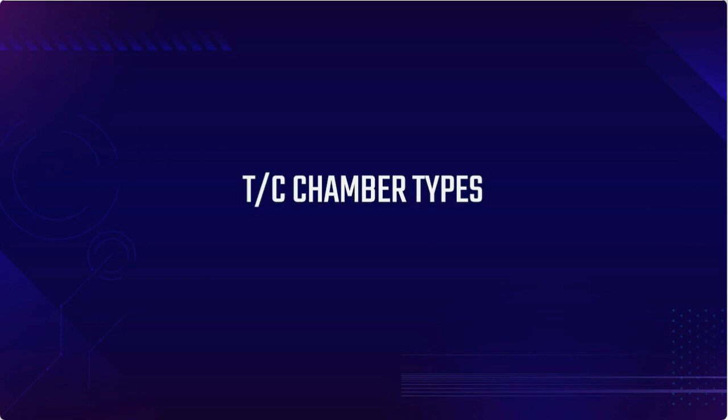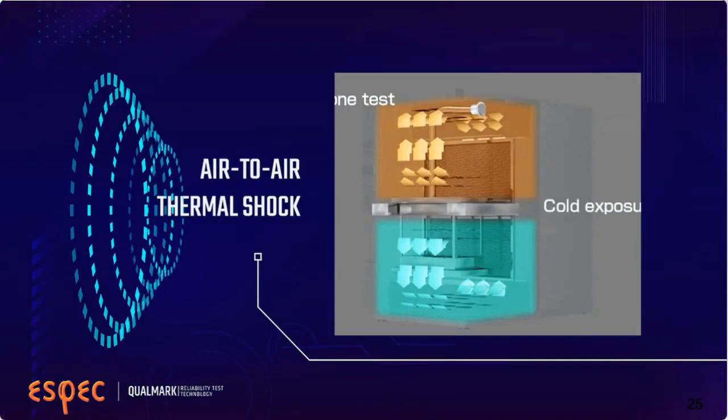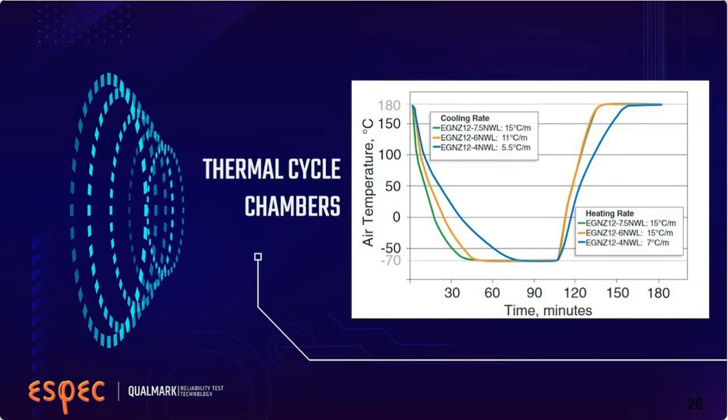Air-to-air thermal shock chambers, which are a specialized type of chamber, and the super-fast liquid nitrogen cooled HALT equipment that Neil talked about. Now, thermal shock is a dedicated type of equipment for instant temperature changes. Thermal shock is commonly used to meet specific test standards and is usually targeting components and not assemblies. It is a transfer or damper mechanism for the instant temperature shock effect.